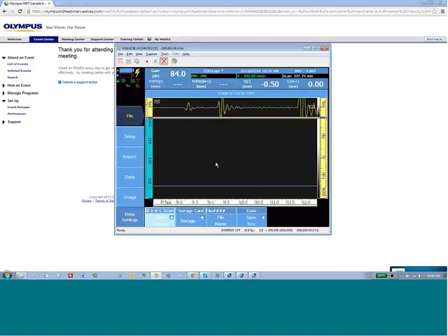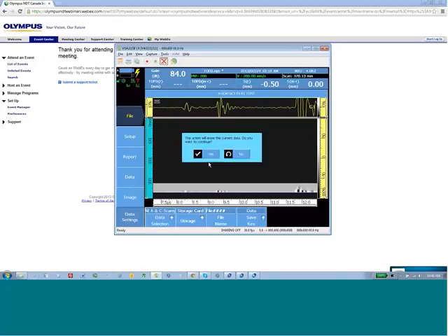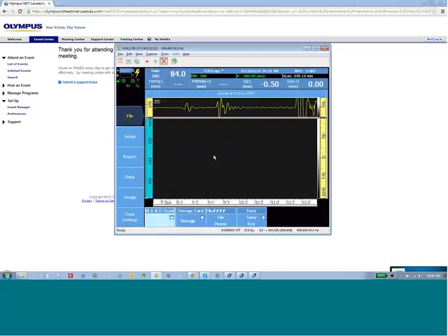I'm going to take a small acquisition here on the plate. So we're going to wet down the plate well. I'm going to position the scanner in place on the component. I'm going to select the start button on the instrument and hit yes. This will zero the encoder and prepare the instrument to take an acquisition. I'm going to move the scanner slowly and smoothly, acquiring the data.